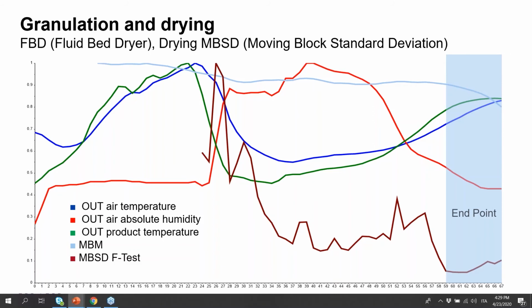You see how clear the endpoint of a drying process is with the NIR, definitely better than the other normal measurements. It's important also to consider that we are measuring a chemical entity and not a physical parameter that is changing upon something else that happened. So here is a direct measurement of water content somehow.